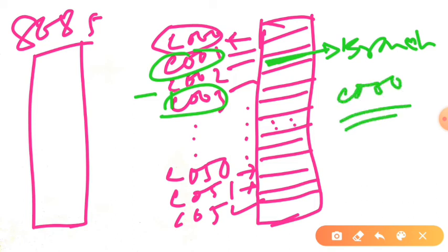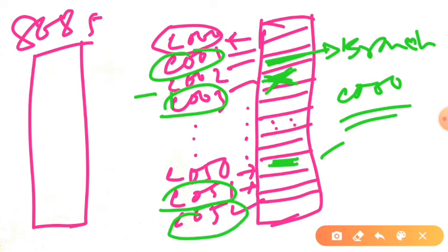Then the next instruction will be fetched from memory location C050 instead of C003. Fetching is completely shifted to C050. The next instruction will be fetched from C051, then the program counter is incremented by 1 and C052 is fetched, and in this way the program sequence goes on.